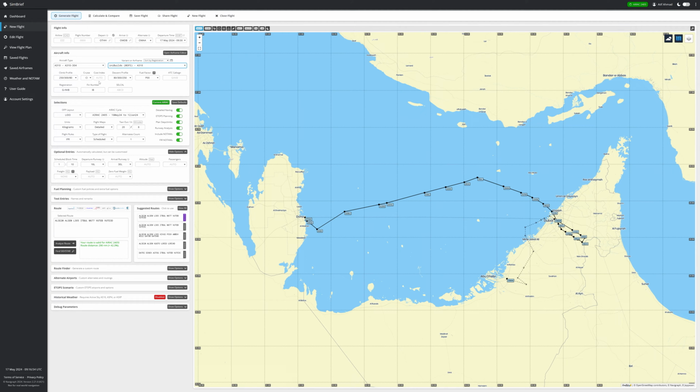Then you have to enter the cost index. It's a number which determines the fuel burning rate of the plane. The higher the number, the more fuel is burned and the plane goes at a higher speed. The smaller the number, the plane goes at a slower speed, the range increases, and less fuel is burned. For this video, I'll use 40, but you can also use 50, 60, 70 or 80. Just remember, the higher the number, the speed increases once the plane is cruising. It's actually a number the airlines use, but for your flight simulation, you can use any number as per your convenience.